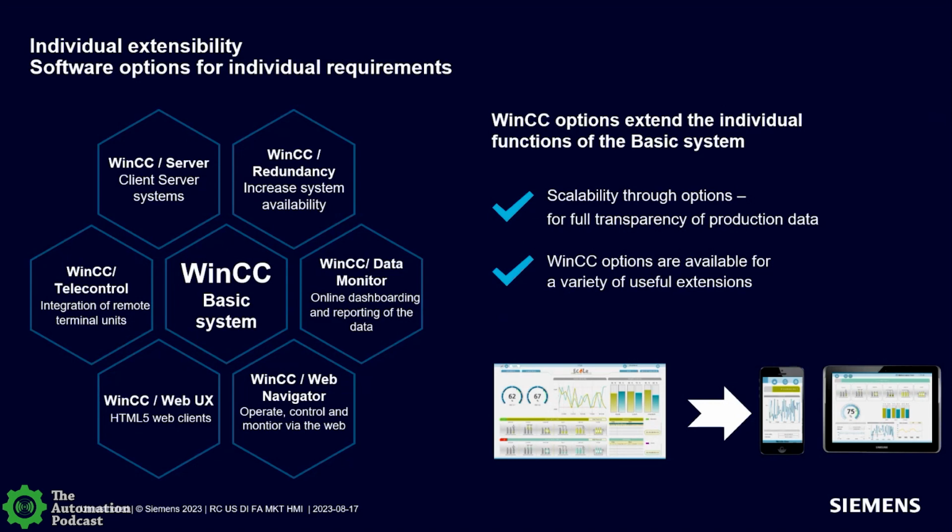Instead of the regular thick clients where I have a WinCC station sitting out there talking to WinCC Server, we have a couple different options for web-based server client or web-based client capabilities. And one of them is Web Navigator. We've had Web Navigator out forever.